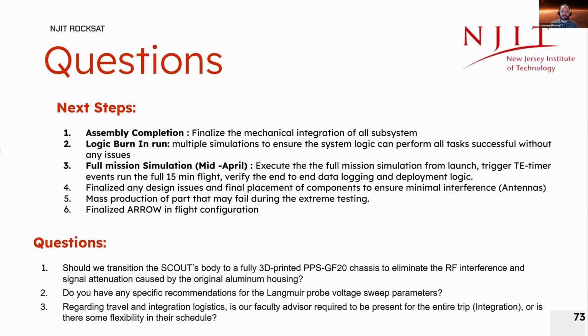So hardware rich, test it till it breaks idea, which will give you a lot more data than the simulation, even if it's more than the spring pressure. Keep in mind that in the testing you're going to be going through, at least in the full z-axis, you're going to be seeing that 25 Gs, both sinusoidal pattern and that random pattern, but also in the XY. I think the XY has me a little bit more concerned just because it's going to be pushing on those tabs.